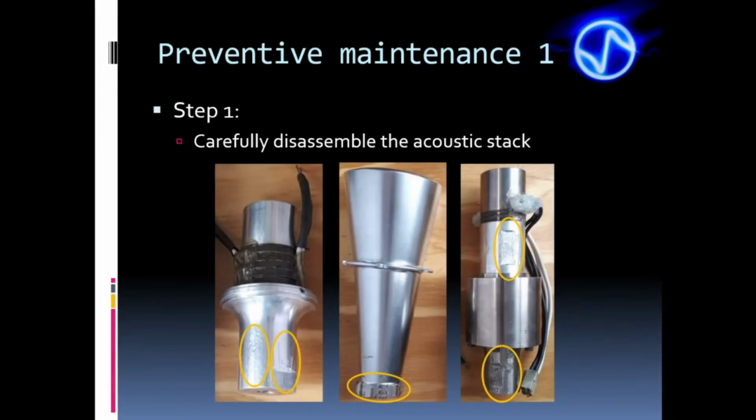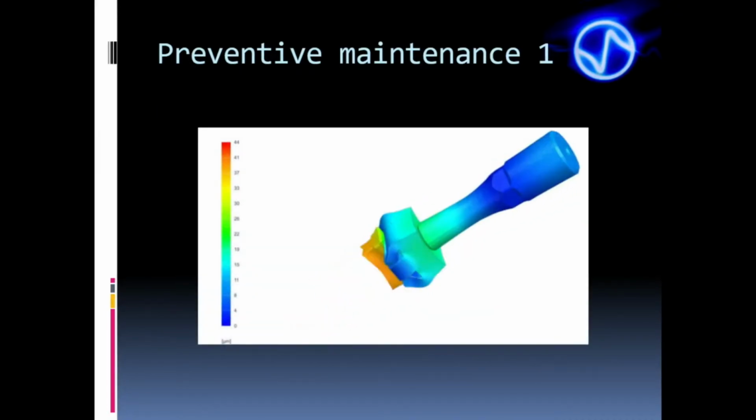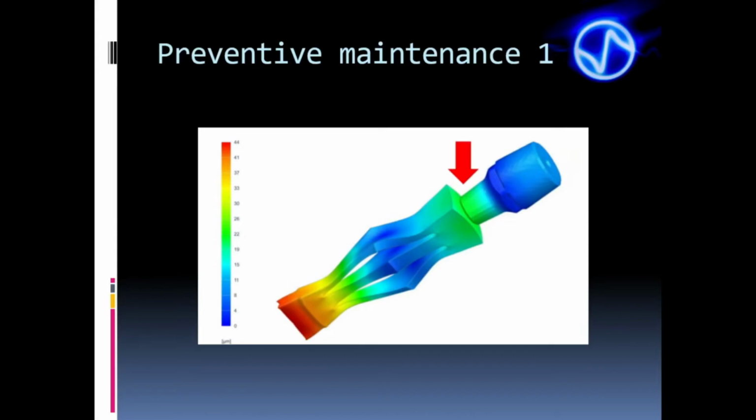As well as affecting performance, superficial damages are regions of stress concentration and crack nucleation during vibration at ultrasonic frequencies and high power. This means that the ultrasonic vibration on the stack may cause the crack at these damages. In an ultrasonic stack with superficial damage, the energy dissipation at the interface causes heat and fatigue, while the superficial damage causes stress concentrations. All this combined can lead to cracks in the acoustic stack elements. That's why this care is necessary during the maintenance of the stacks.